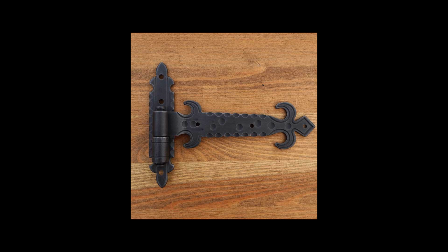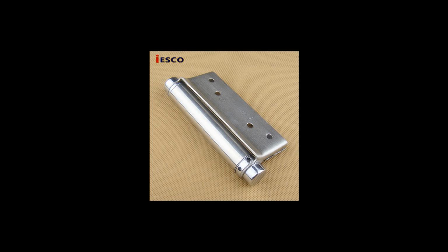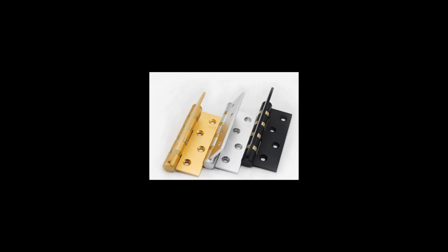Hinge length. The length of the leaves parallel to the pin. Knuckle length. The typical length of an individual knuckle parallel to the pin. Leaf width. Length from the center of the pin to the outer edge of the leaf. Pitch. Distance from the end of a knuckle to the same edge of its adjacent knuckle on the same leaf. Slop. A colloquialism referring to loose angular movement of the leaves relative to the pin.